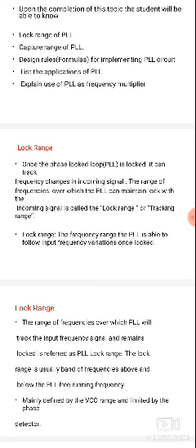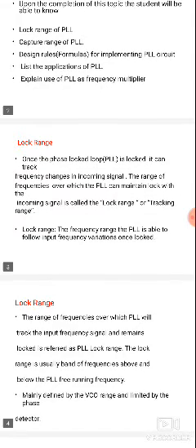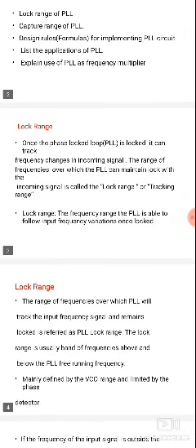Next, we also discussed the 565 and 566 ICs in previous classes. The 565 IC is a 14 pin IC. One pin is for ground, pins 2 and 3 are used for input, the 4th pin is for output, the 5th pin is the VCO input, and the next pins are for discharging, an external resistor, an external capacitor, and supply. Pins 11, 12, 13, 14 are no connection pins.